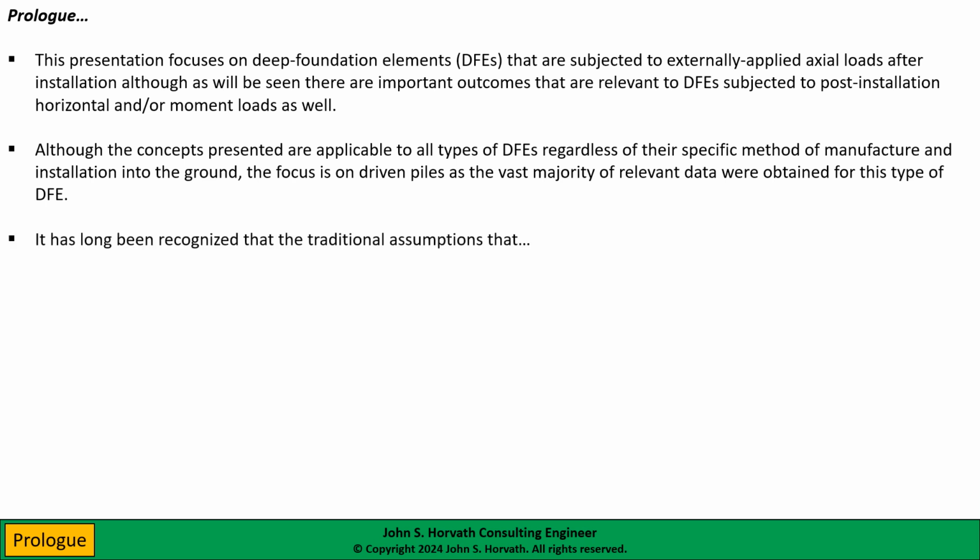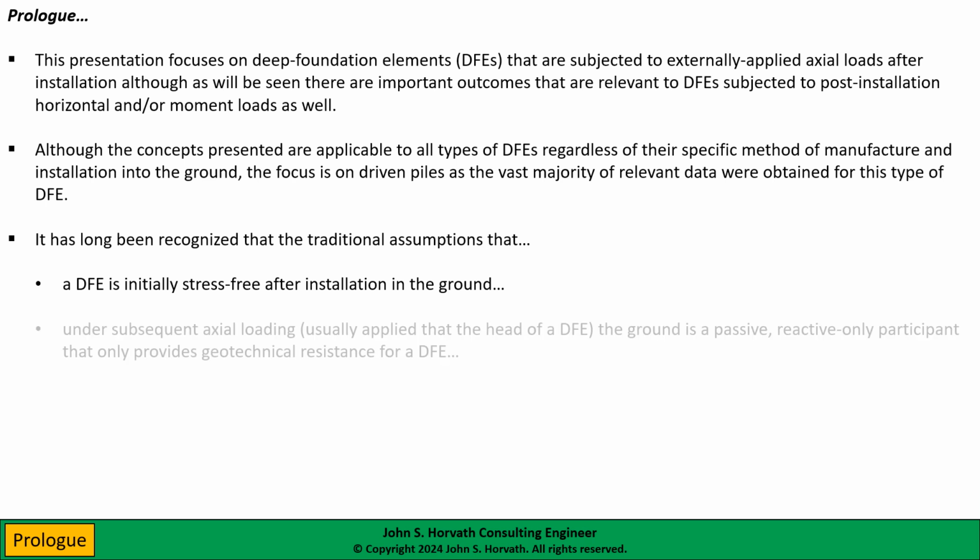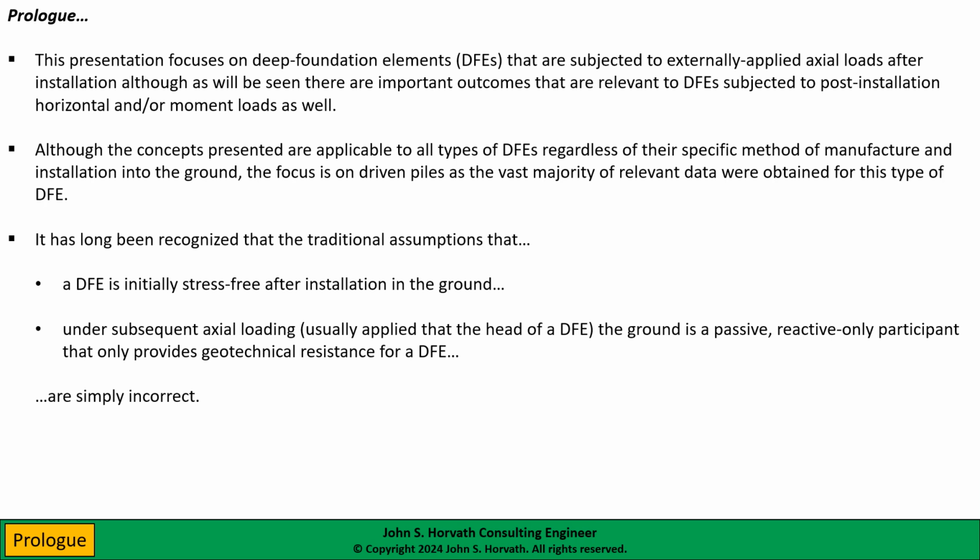Now, it has long been recognized that the traditional assumptions that a DFE is initially stress-free after installation in the ground, and under subsequent axial loading, which is usually applied at the head of the DFE, the ground is only a passive, reactive-only participant that only provides geotechnical resistance for a DFE. Well, these two common assumptions are simply incorrect, and I'll explain why as we go through this presentation.